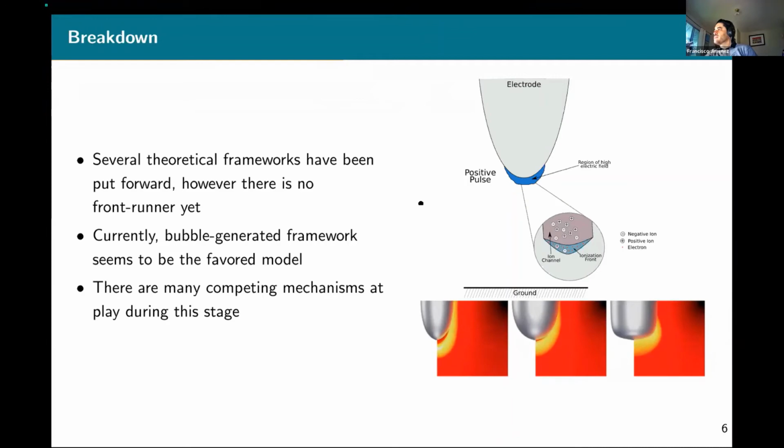In this case, I'm showing a simple two-fluid model of a plasma built in OpenFOAM, where given that the mean free path of electrons in a liquid is very, very small, we can, as a first approximation, ignore the solution for the electrons and concentrate on ionic species, which are coupled with a Poisson solver.